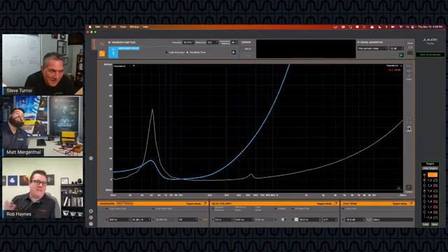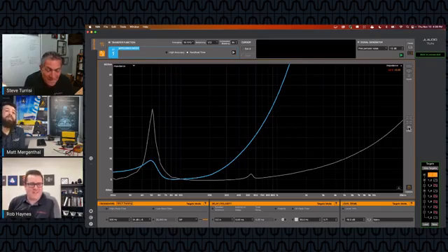All right, so I'm going to guess W7 just because I know how large those coils are. So hold on, I got to make this fair. These last three are not specific JL Audio products. So just give me the size, and if it's in an enclosure or not in an enclosure, try to give me that without the product specific. All right, I'm guessing not an enclosure. The resonance is pretty low on that. It's a subwoofer, pretty stout coil on it. Lots of inductance there. I don't think it's an 18 like Josh is thinking. I'm thinking maybe a 12 or something.